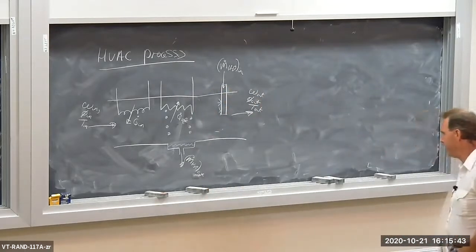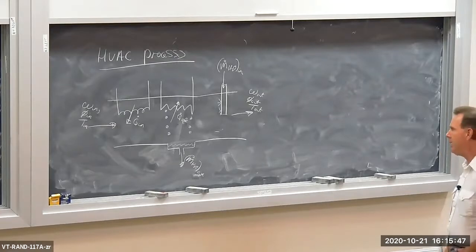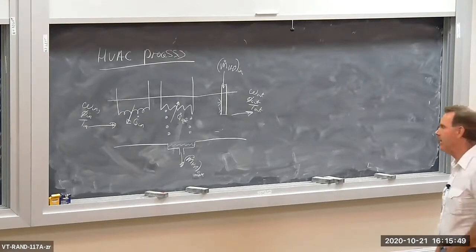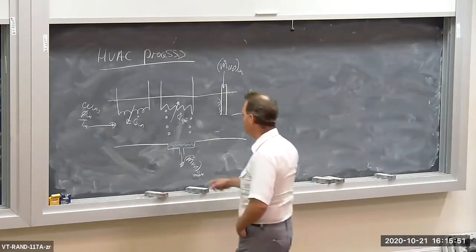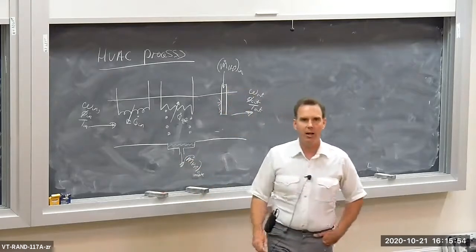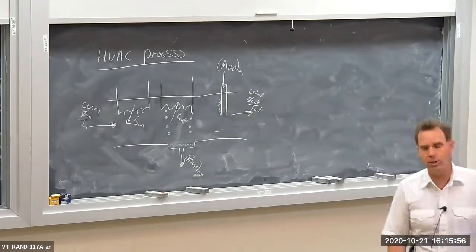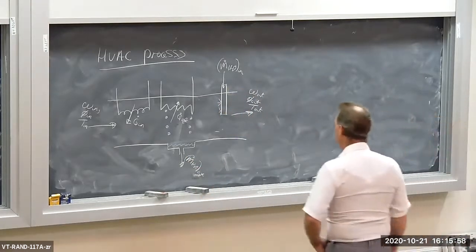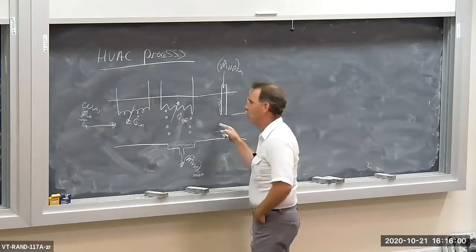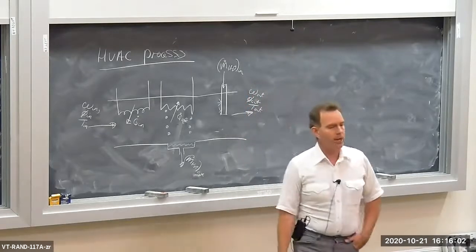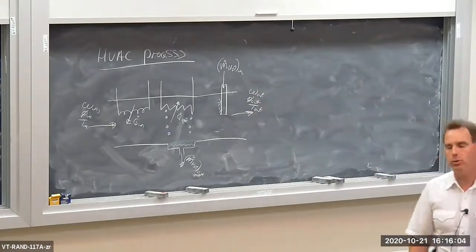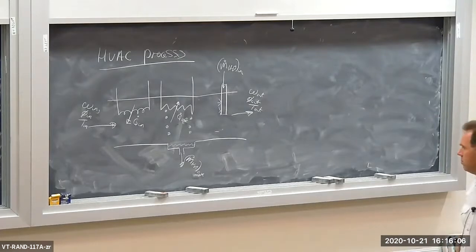So a possibility here is cooling, heating, and the cooling may contain dehumidification, where we drain away some of the condensate, the H2O condensate. And we can also have humidification going on by spraying H2O into the duct or the device. Okay, so there's all these possibilities.